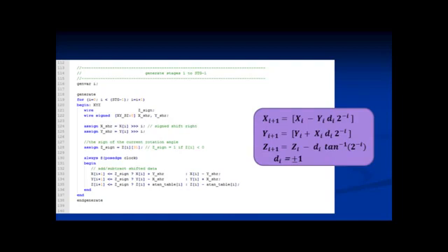calculated based on the current value of z and the sign of the angle, which determines whether we add or subtract the arctangent value from the table. Actually, the way the Verilog code is written, there is no table actually generated. It's merely that the appropriate constant is used in each stage of the pipeline. I use the term table because it's easier to understand when initially discussing this topic.